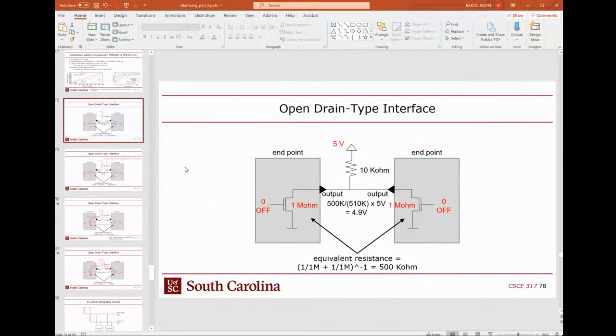But we're not talking about differential links here. We're talking about single-ended, meaning 1 wire per bit. So all of the wires sent in these channels would have to have a common ground. It wouldn't necessarily have to be the same ground as other logic on the chip, but there would have to be a ground for the channel. So thank you for asking. That's a good question.